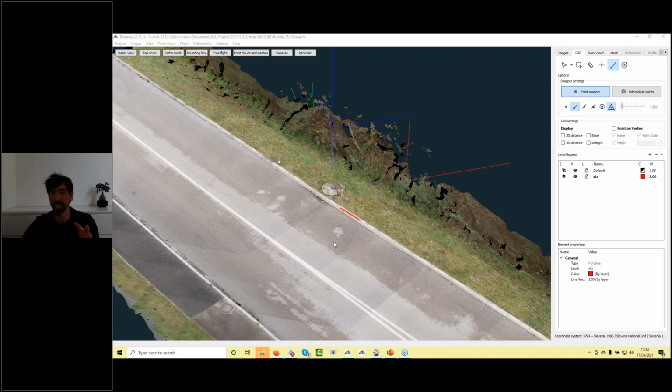But nevertheless, Phantom 3 Pro also works. You can, if you take a bit more time, place more ground control points, fly maybe a bit lower, because I think it has a 12 megapixel camera. I will go on 60 meters or 50 meters, something like that. You can also go with this one, definitely. Okay.